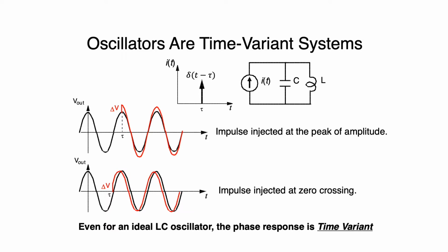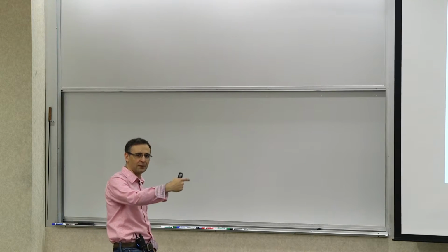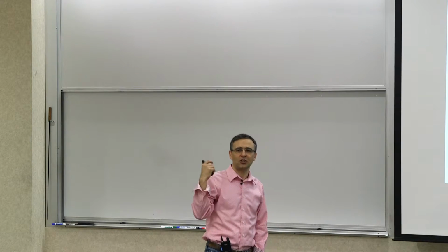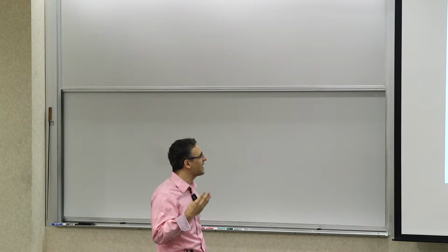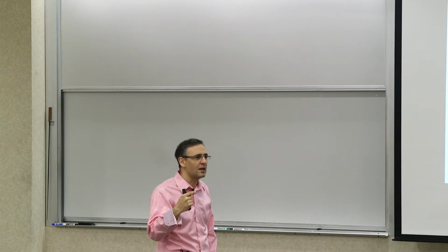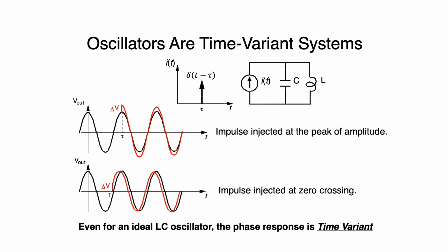And it comes in, and the impulse hits the oscillator. The oscillator is already oscillating; there's some energy in the tank, and it keeps going back and forth. It produces a perfect sinusoid, the black curve. At some point in time, you inject an impulse into this. The impulse is going to go entirely through the capacitor, and it's going to instantaneously change the voltage across the capacitor because it will inject charge into it. So if your injection is delta Q, then delta V is proportional to delta Q divided by C. Q is CV, right?